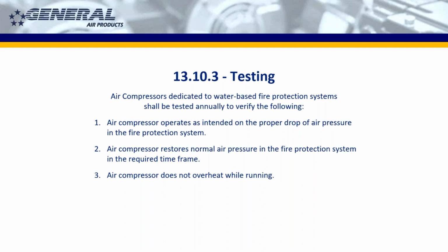But if it runs for 2 seconds and it's still hot, or if it's always running, maybe that's what's causing it to overheat. Not so much a bad voltage, which can also cause it to overheat. But at any rate, when you start to think that a compressor is overheated in this regard, just call us and we'll help you zero in on what the problem is.